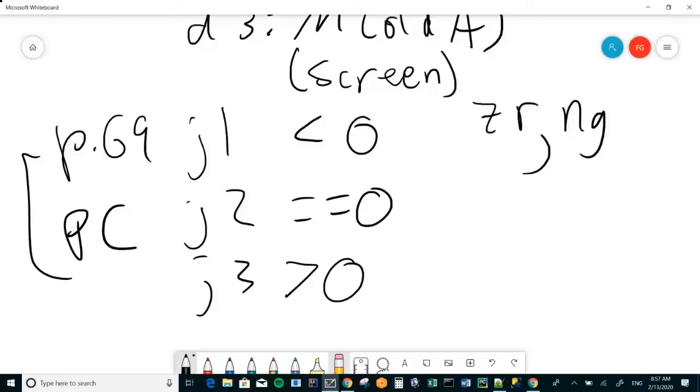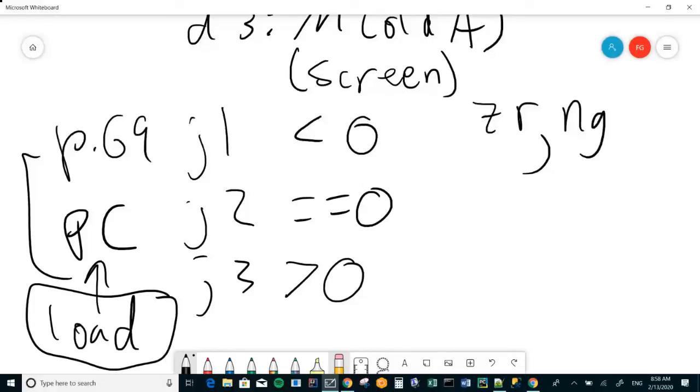And in this case, you're going to do it right here. So for each of these, you've got circuitry indicating, does this hold? Am I going to jump? And then in effect, you just OR them from there, because if more than one of these is a 1, any of those conditions being a 1 is sufficient to cause a jump. And if you're going to cause a jump, it comes back to the PC, and it comes back to the all-important load bit that determines a jump. And we looked at that last time when we were looking at our super made-up Turing machine CPU.